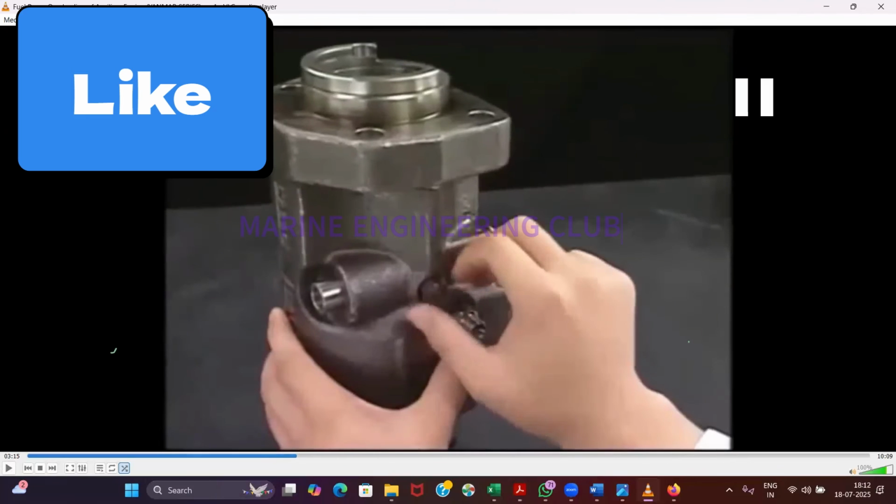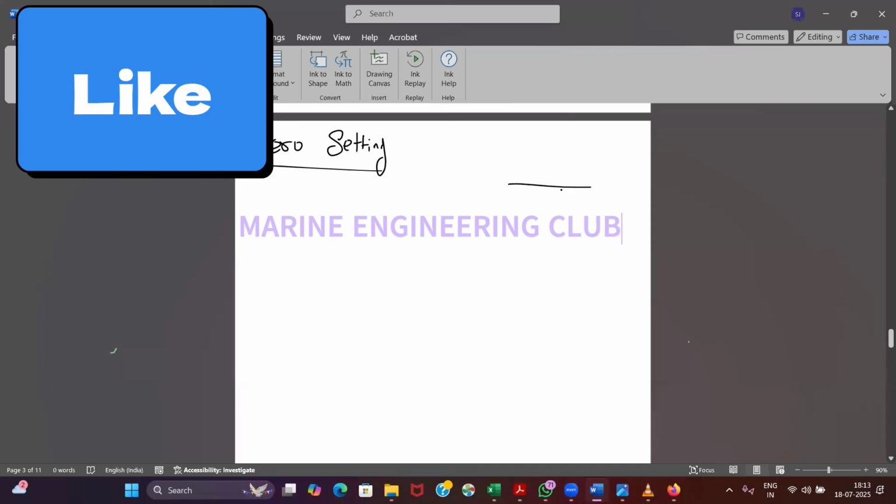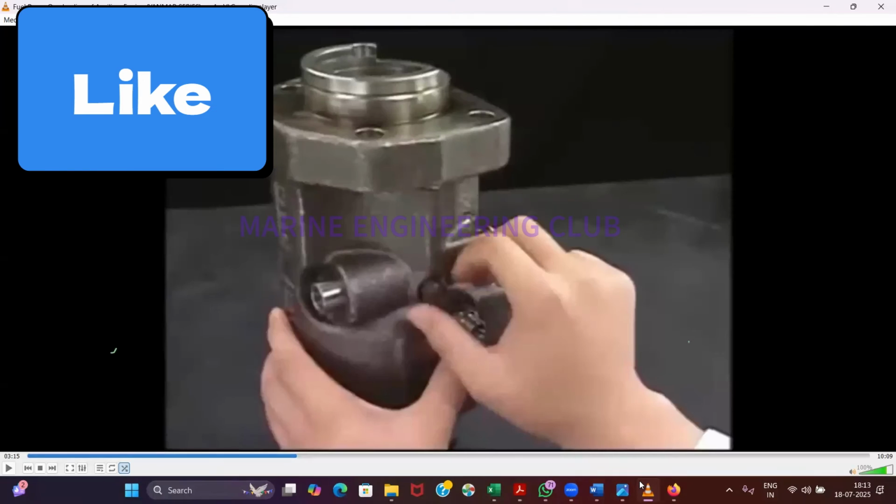Now what he is doing right now is removing the rack. On the rack there will be one slot, on the back face of your rack, and there is a locking pin going here. So the rack movement is only restricted to this much area, isn't it? This is known as the locking pin. If you have to remove the rack, you first have to remove the locking pin, and then you can pull the rack out.